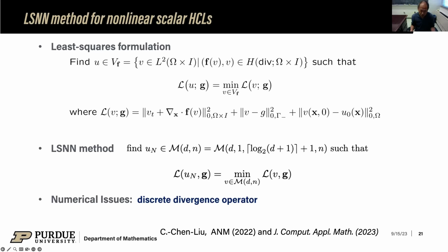Again, in order to make this work, we have to talk about three things. One is the numerical integration. That's basically how to choose the integration points to give you the right information. In the example, adaptive numerical integration is slightly complicated, so we just use a very fine integration mesh. In that way, we don't miss any important information from the problem.